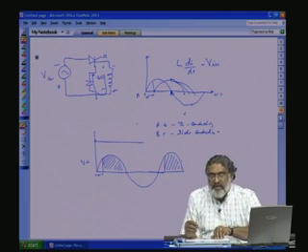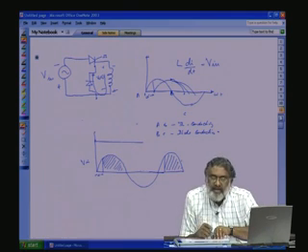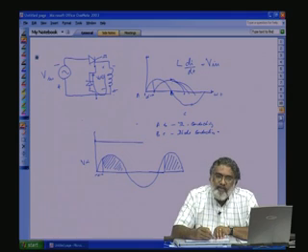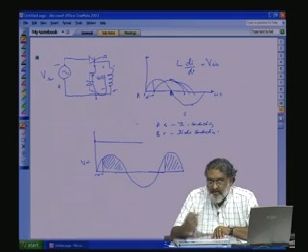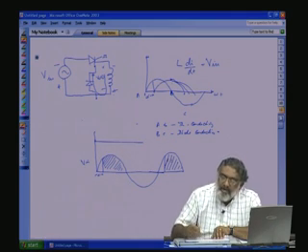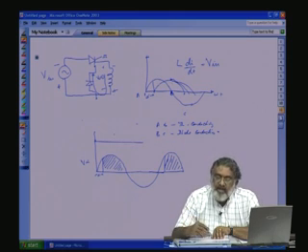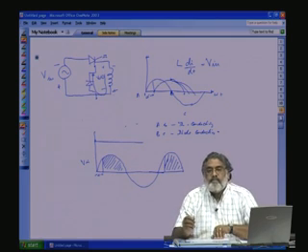So this voltage ripple across the load, now the load is, whether it is resistive or inductive, we don't have to worry. With this freewheel diode, automatically this voltage ripple will appear across the load, and this equation is valid for the output V0 volt. V0, that is a DC value with respect to firing angle alpha.